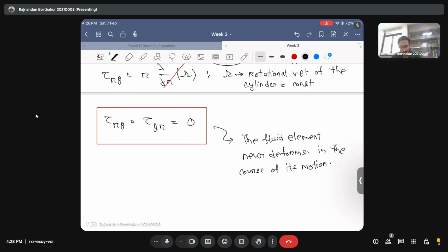So in summary, there are two takeaway things in this special case, where we don't have an inner cylinder and we don't impose any pressure gradient in the z axis. Number one, in the r direction, although there is no velocity field ur, there is an induced pressure gradient that gets developed in order to tackle the centripetal force, which is trying to move the fluid outward. It basically balances the centripetal force, such that the fluid continues to circle around in its orbit. That's the number one thing.